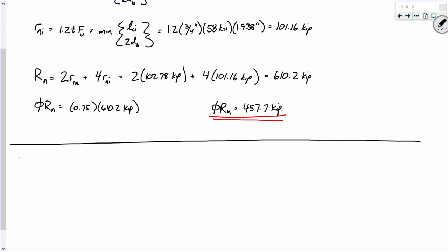So we're going to look at case 2. We're going to look at the cover plates. Now here's the easiest way to handle this. Number 1, when we did the main plate, we started listing some parameters like what's the bolt spacing, what's the thickness, and so on. So let's just keep that same pattern. So for cover plates, what's the bolt spacing? 3 inches, nice and simple. Now, here's the kicker. What is the edge distance? This is one point I want to make right now. What's the edge distance? 2 inches. For the cover plates, it's 2 inches.